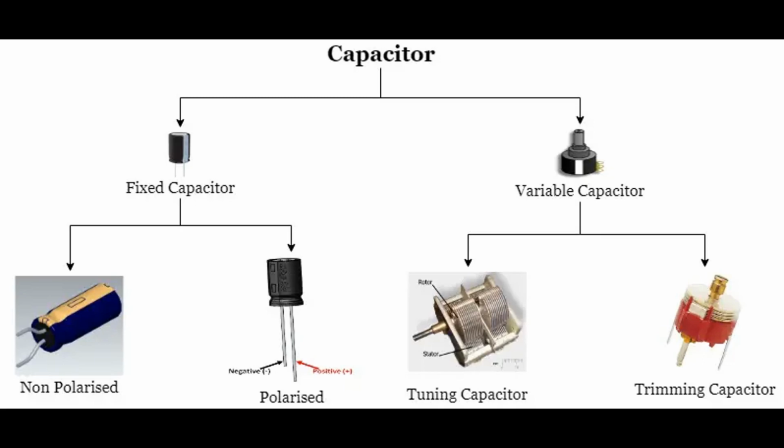Tantalum electrolytic capacitors. Tantalum capacitors have a tantalum metal electrode as the anode and a conductive polymer or electrolyte as the cathode. The tantalum anode is coated with tantalum pentoxide, Ta2O5, which serves as the dielectric.